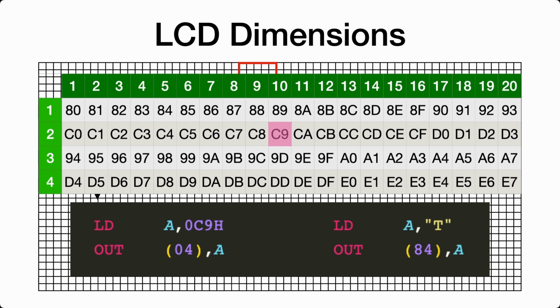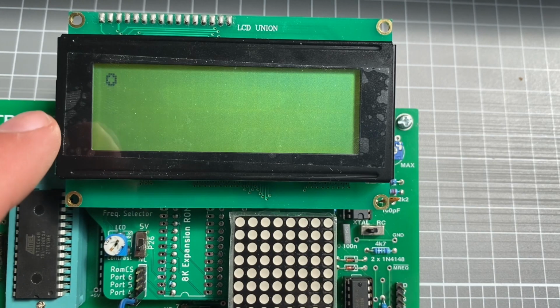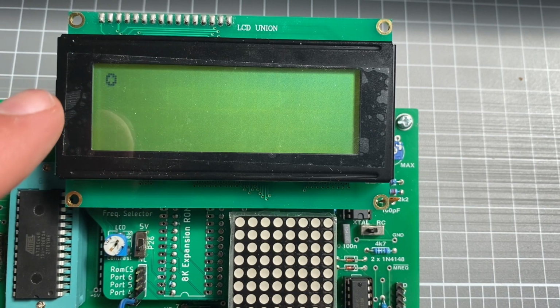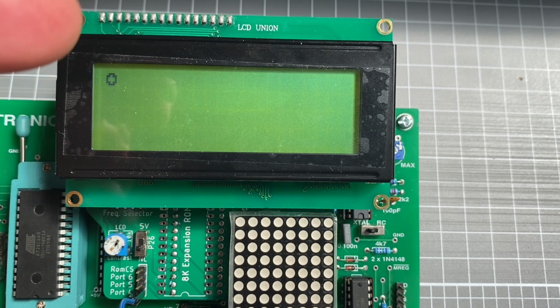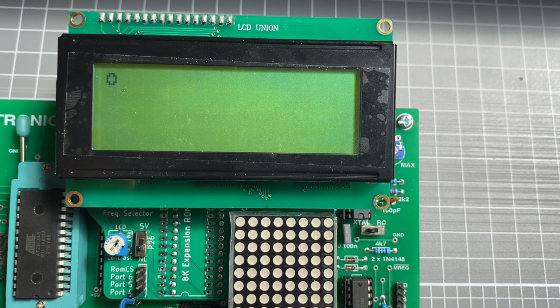That will move the cursor to position C9, and then we just send the character, let's say T, as data. Okay, I've got a ball now displayed at the top left-hand corner, 1X, 1Y. Now remember, I've got 5 characters to move across and 8 characters down for it to go to the next character position. Although you can't see me press any buttons, you can hear me.